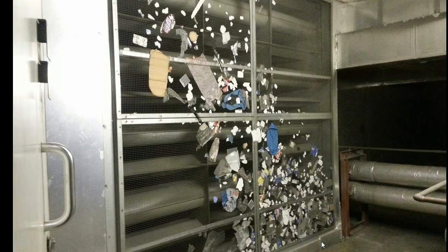So this intake was positioned near the bins of the building, and if this mesh hadn't been there, then this could have potentially been sucked into the fans. It should have been picked up by the filters on the other side, which we'll look at in a bit, but it still could have built up on the inside and caused some damage in there. So it's good to have a grill on the outside first to catch anything, stop any animals or anything getting in there, anything that could cause any damage. And it's obviously important to clean this off periodically as well.